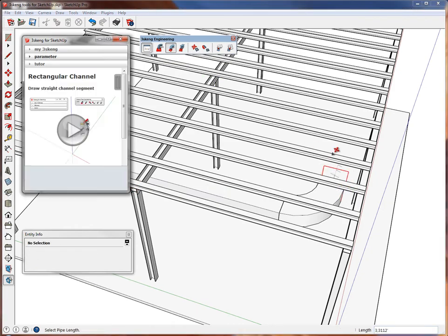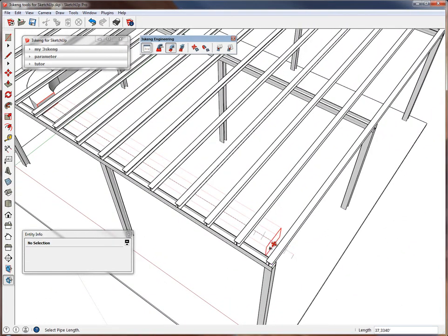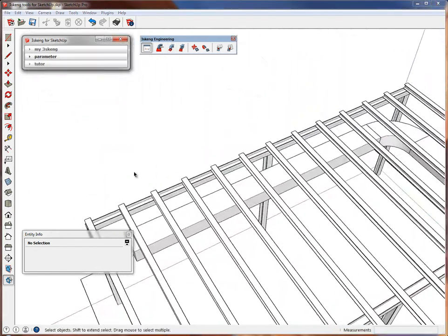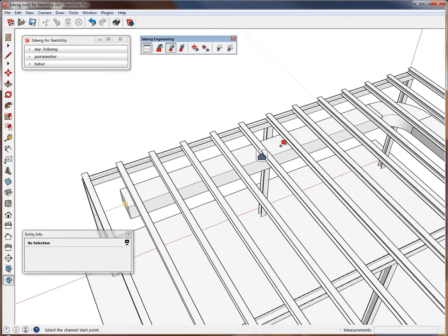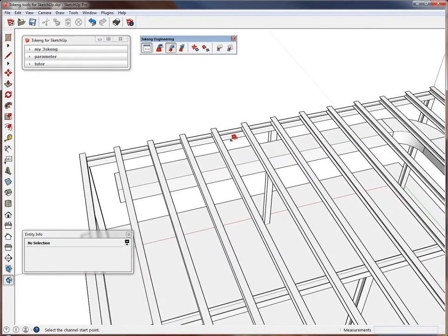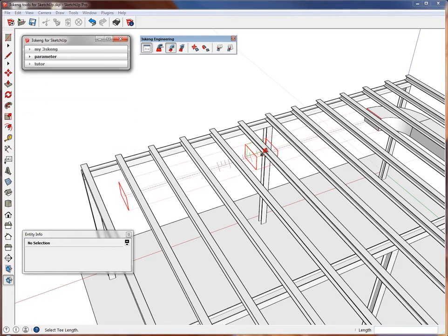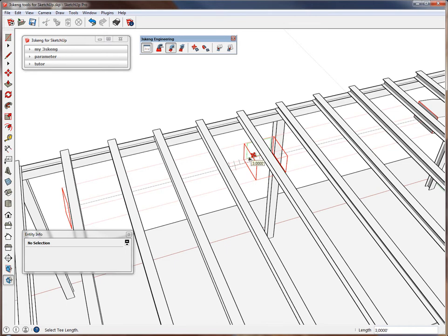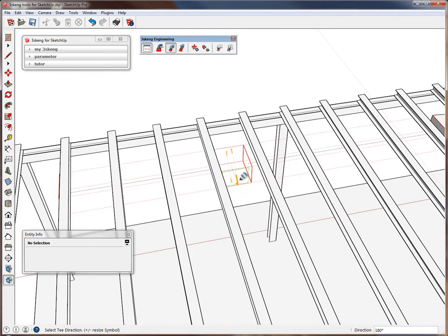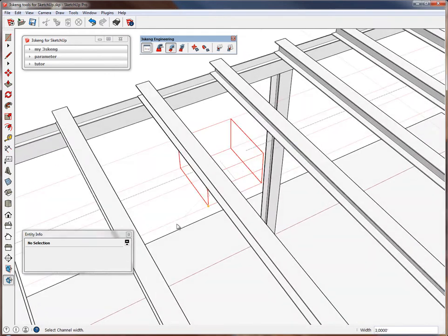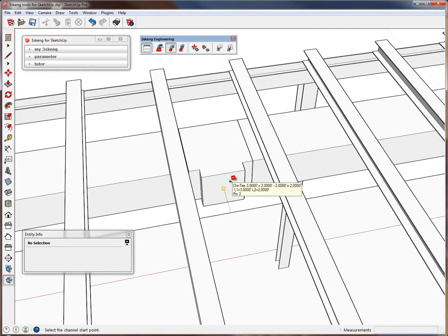We will attach another straight piece with a random length. So now we want to add a T-piece in our duct. We can do it in 2 different ways. By clicking the T function in the channel tool, we can either attach it at the end of an existing one, or we can put it right in an existing channel, which I will do in this case. First step after this is to indicate the length and its position. Second is what direction the branch will look. We'll just have it face this way. And the other step is to indicate the length. We will just go with 2 by 2, and now our T-piece is already finished.